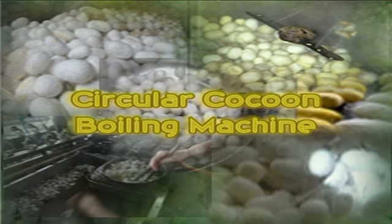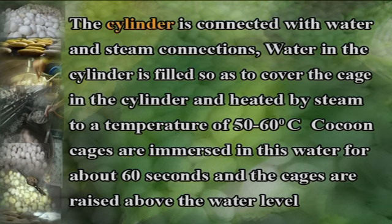The circular cocoon boiling machine. This is a batch type of pressurized boiling machine. The equipment consists of a cylinder with a lid mounted on a stand, with cocoon cages provided in the cylinder, with provision for lifting and lowering of the cages within the cylinder placed on the platform. The cylinder is connected with water and steam connections.